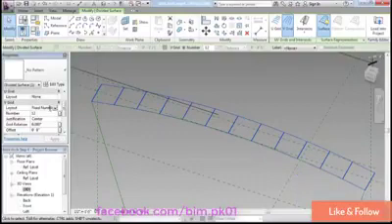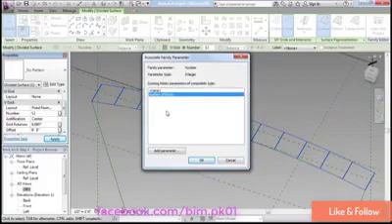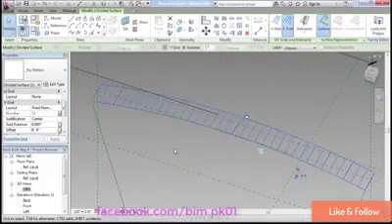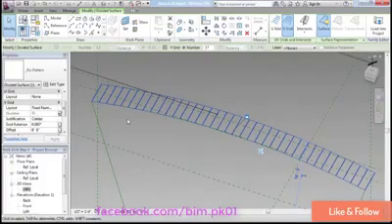Now in this direction, the layout is currently set to a fixed number, and that fixed number is currently just 12. Now 12 is somewhat arbitrary. That's just the default number that Revit uses. Well, notice the little button right here? I'm going to click on that, and I'm going to assign that to number of bricks. Now we painstakingly calculated the exact number of bricks that we needed in the previous movie by writing out that very detailed trigonometric formula. So now I'm just going to link that parameter up with the division here, and you'll see that number of spacing, 37 in this case, gets applied to the curve, and those are our individual bricks.